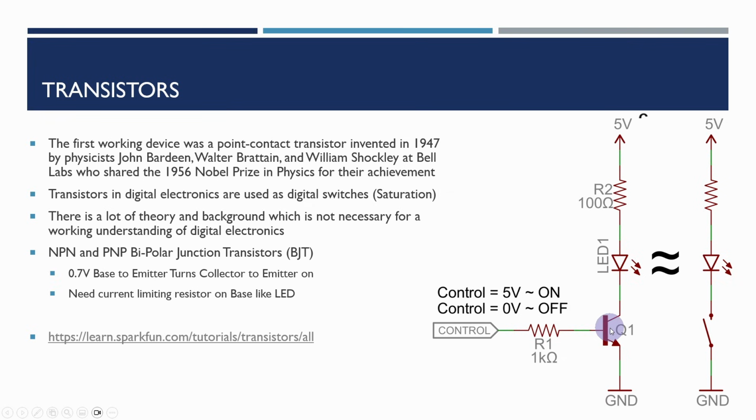So what we have here is an NPN transistor, and PNP is the other type. So the arrow not pointing in is the NPN. And you'll see these called bipolar junction transistors. The thing about being bipolar is that it's, I guess, the older technology. More modern transistors, certainly in modern chips, are CMOS, complementary metal oxide semiconductor. But we're going to be dealing with bipolar, and the TTL logic, or transistor-transistor logic, which most retro digital electronics uses, is using these bipolar junction transistors.